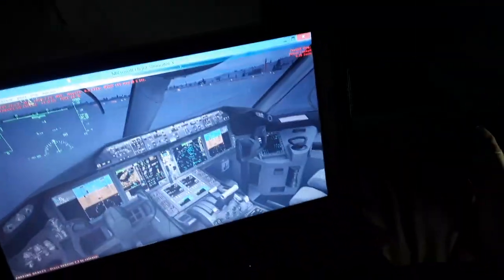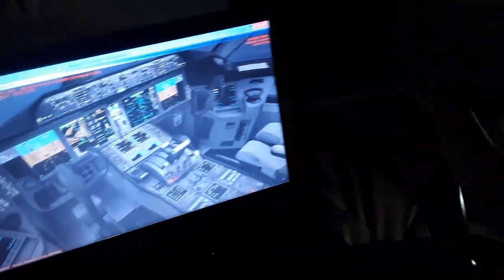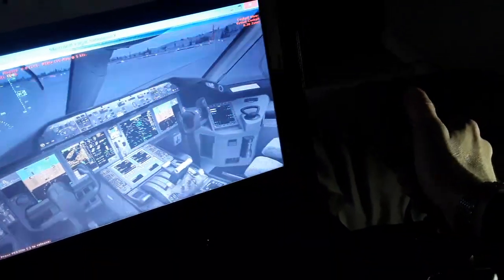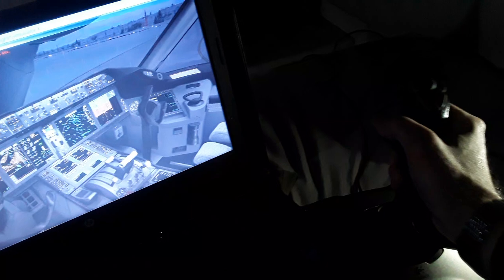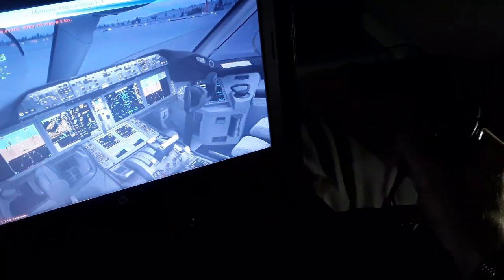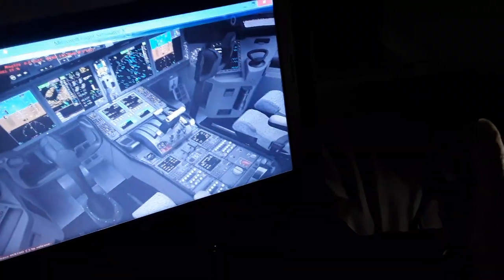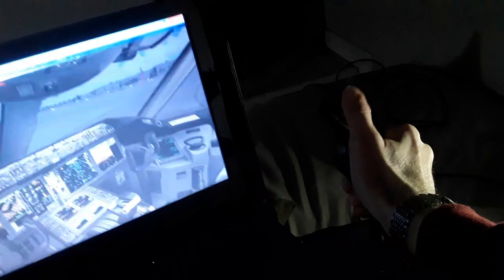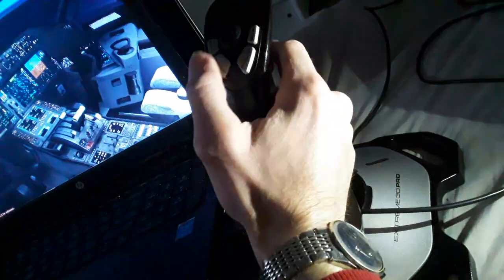As you can see, both side sticks are moved together in the Boeing, are interconnected. Also the rudder pedals in the Airbus are interconnected. In the Boeing you have to use some force in either side to override. In the Airbus you just need the side stick priority button. Rudder pedals are interconnected in all airliner aircraft, both sides: Airbus, Boeing, Embraer, CRJ. So we have the side stick priority or dual input.